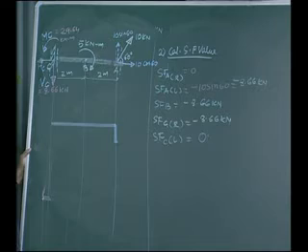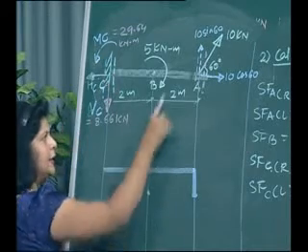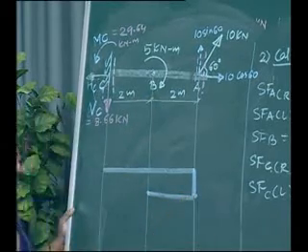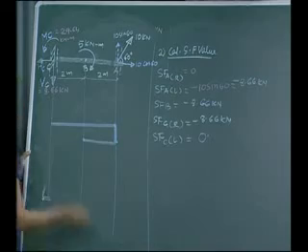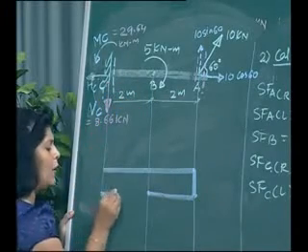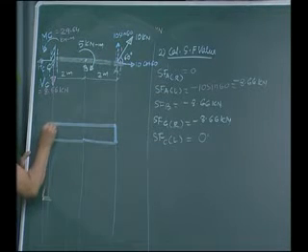So we have to draw a vertical line. Shear force at point B, again 8.66. No load between A and B, it will be a horizontal line. Shear force at point C, just right, again minus 8.66. No load between C and B, again it will be a horizontal line. And shear force at point C, just left, 0.